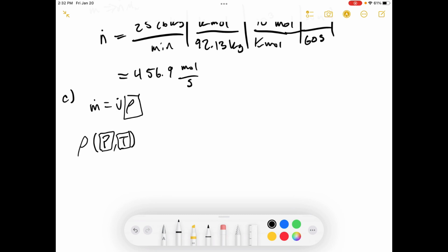If we were working with a gas, there's a lot more space in between gaseous molecules. Filling up a gas cylinder, for instance, you put in a ton of gas, you increase the pressure of that gas tank, the density is going to go way up. And so it's a strong function of pressure in its gaseous state. So you have to be careful about when you make that assumption. Is pressure going to make an impact on your density, or is it not? And then you also have to make sure you have the right temperature, because that will also change your density calculation a lot as well.